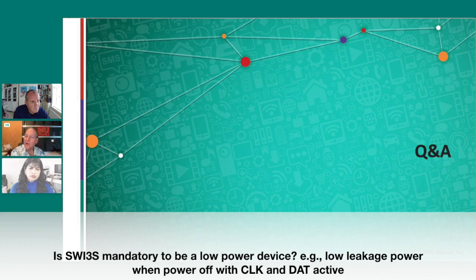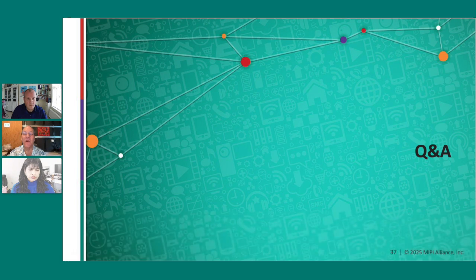So you are still allowed to build a device that uses a diode from one of the pins to VDD on your part, which would be problematic if you're going to withdraw power from that part. If you're a system integrator that wants to aggressively manage power, then you need to be telling your device makers that they need to do something smarter on their ESD protection so that you can do that. Did we get it?